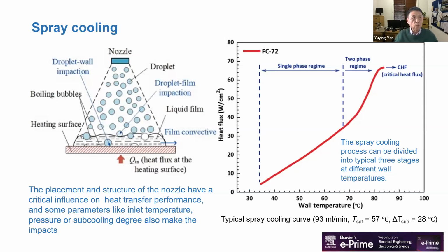This is very important. We mentioned spray cooling. It is probably one of the most effective thermal management technologies for high power electronic devices, due to its capability for high heat flux dissipation and a sizable cooling area. It uses a nozzle to break the cooling fluid down into numerous tiny droplets by high pressure. Then the droplets impact directly on the heated surface to enhance heat transfer.